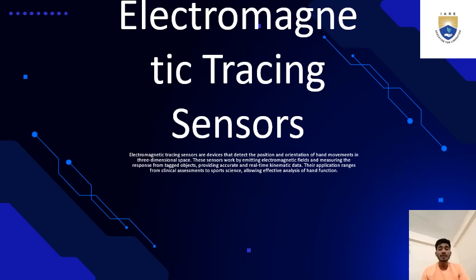Working. Magnetic field generation. The transmitter coil generates a magnetic field. Target movement. The target moves within the magnetic field, disturbing it. Induced voltage. The receiver coil detects the change in the magnetic field, inducing a voltage. Signal processing. The induced voltage is processed to determine the position, velocity, or acceleration of the target.